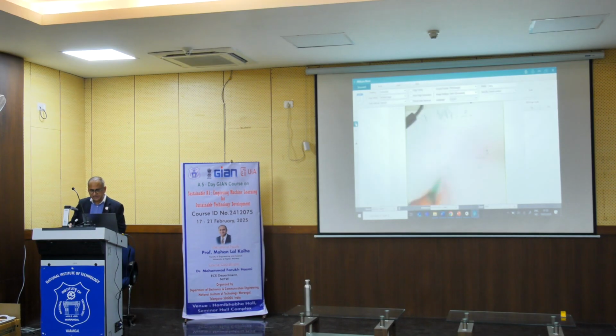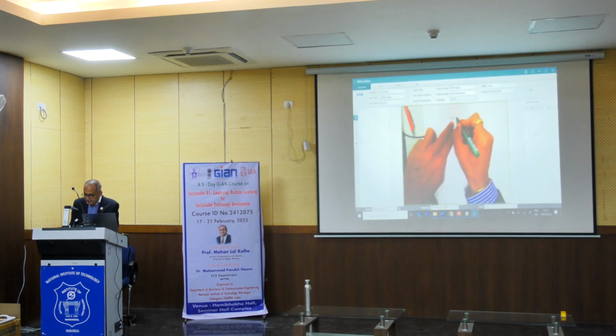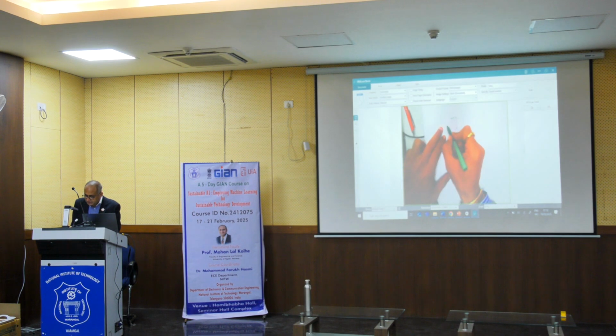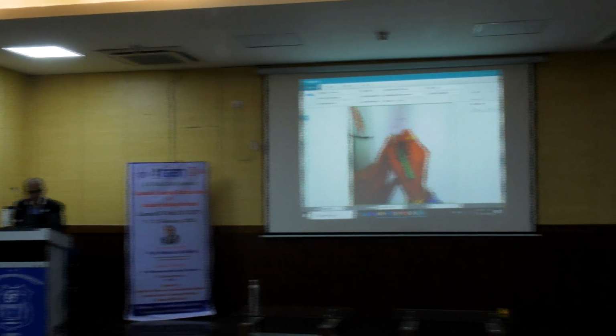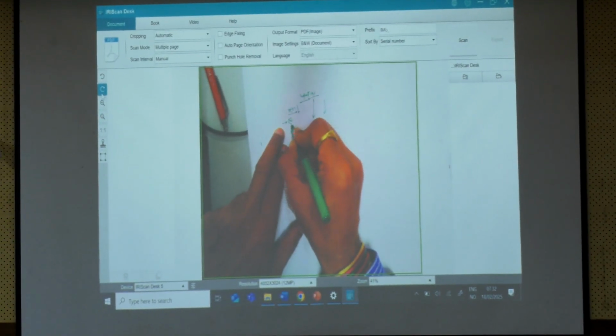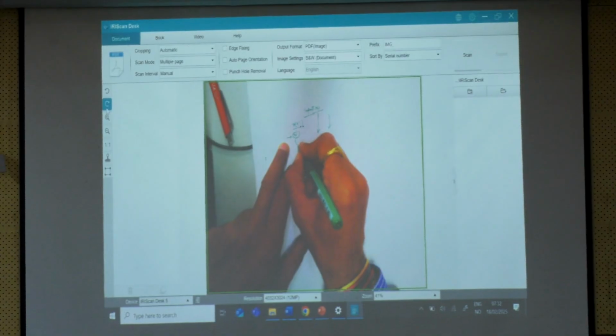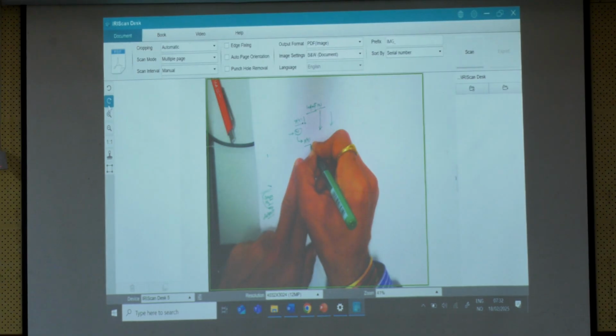So when we have this input, that is time dependent. Here we have the prediction of the wind speed, correct. We will get the prediction of the wind speed. Based on this wind speed prediction, considering technical characteristics of the wind turbine, we are going to get the power output prediction from the wind turbine.